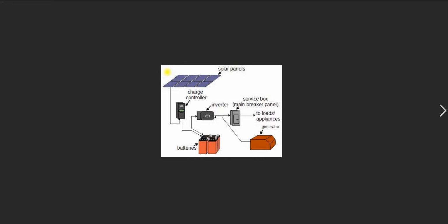That's why there is a third point or disadvantage which says that a solar panel produces DC electricity which cannot be directly used for many household purposes, because the solar panel is producing DC voltage, but we need AC voltage. For that we need inverters which convert this DC voltage to AC voltage. That's why they cannot be directly used. We need a charge controller as well as a battery as well as an inverter which converts it.